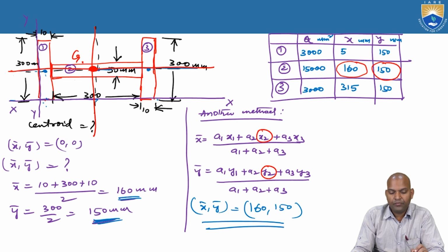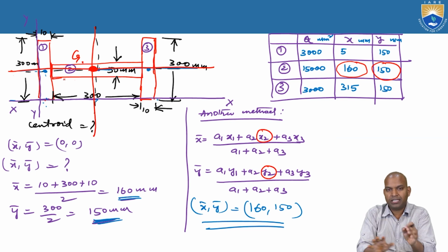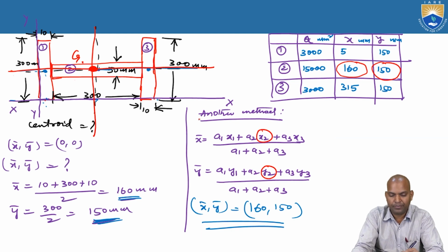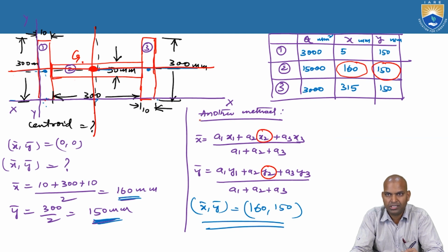Similarly, if you come to the H section and turn it 90 degrees, you can obtain a symmetrical I section. If you consider the I section geometry, bar x and bar y pass through x2, y2. So the two lines of symmetry are easy, and there is no need to calculate this. Another method which I calculated here is no need to do. Why? Again you have to count, and the same thing will be obtained.